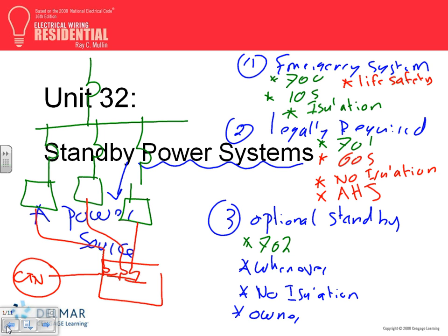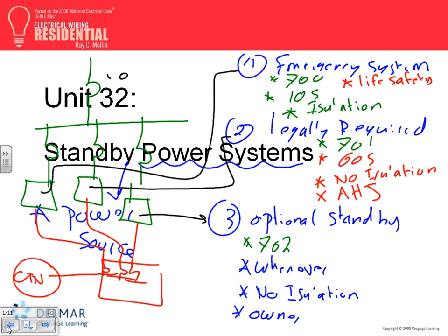And then from the auto transfer switch, the first one is going to be emergency. So I'm going to grab the emergency and go all the way and feed the emergency. The second one would be legally required. I'm going to grab and go feed the legally required. The third one is going to be optional. So you have a power system, say this one a 4,000 amp service coming and feeding auto transfer switch 1, auto transfer switch 2, auto transfer switch 3.